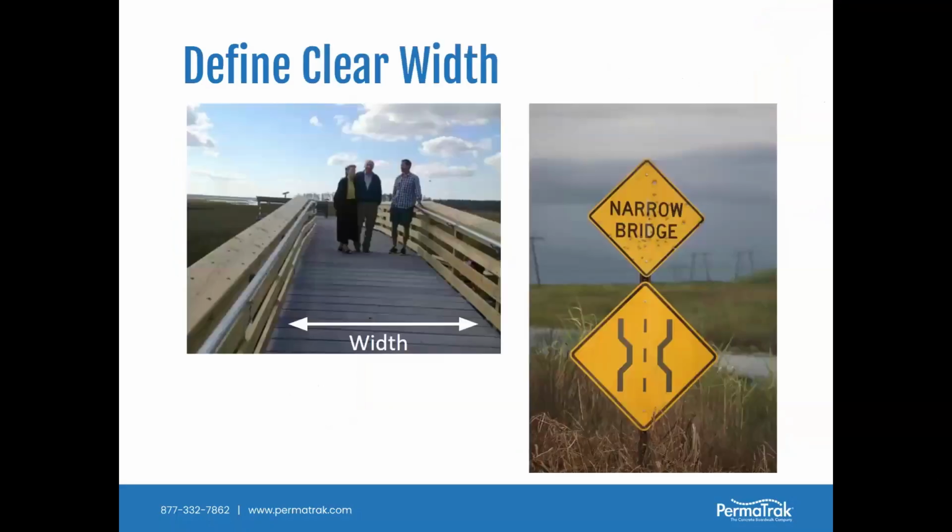And then one thing specific to boardwalks is defining what we know as the clear width. If you've ever talked with a boardwalk designer, whether it be Permatrack or some other boardwalk engineer, one of the first questions that you'll get asked is, what is your clear width? And the clear width is simply your available walkway width within the boardwalk. As you can see in the picture on the left, from the grab rail to the grab rail, the clear distance is measured from those two obstructions. It could be a bumper rail or a tow rail on the bottom of the curb if it didn't need handrails. So think about those side-mounted obstructions.